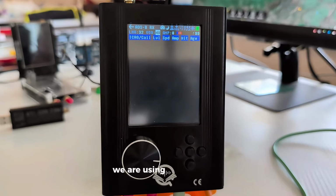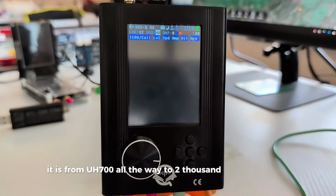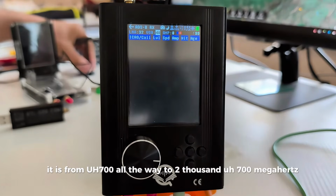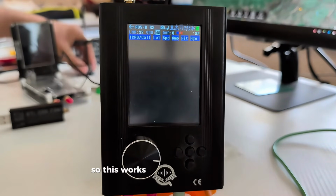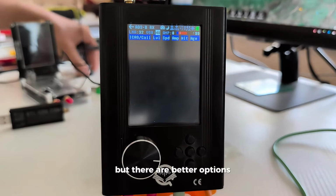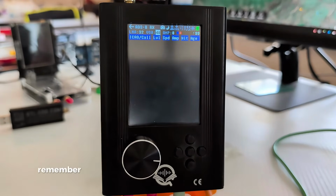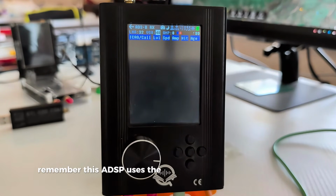By the way, we are using this antenna that comes with the HackRF bundle from AliExpress. It is from 700 all the way to 2700 megahertz. So this works fine for this particular job, but there are better options. If you have better options, just use them. Remember, ADS-B uses the frequency around 1090 megahertz.